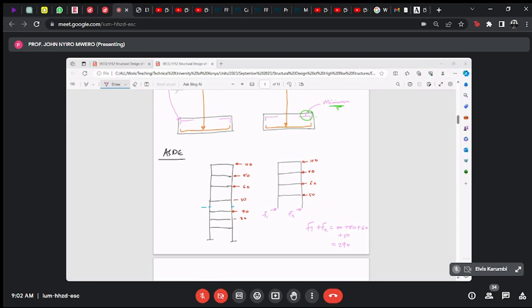So it carries axial load, but the governing criteria would be bending and shear. Even the shear is just a check, because it's a very large area that is resisting the shear. Rarely do you have a problem if the wall is adequately sized in terms of shear. So you first design the wall to carry the bending. If it carries the bending and you're comfortable, then you can check these other things, and most probably they will be adequate. If the bending is not adequate,